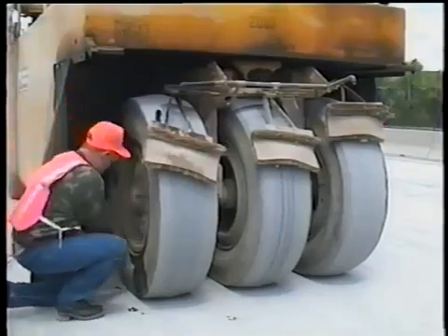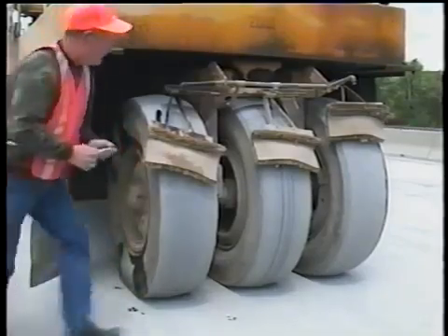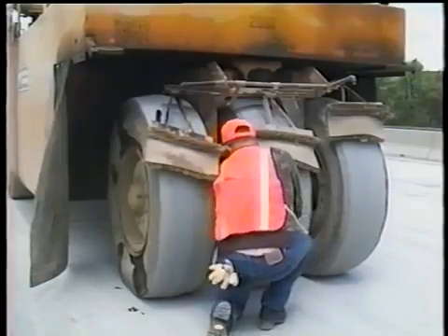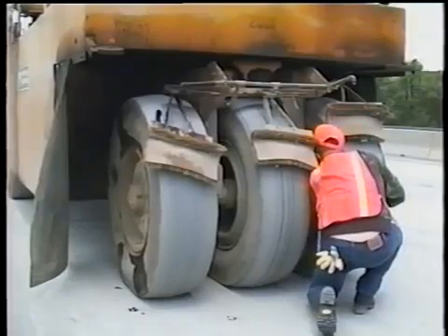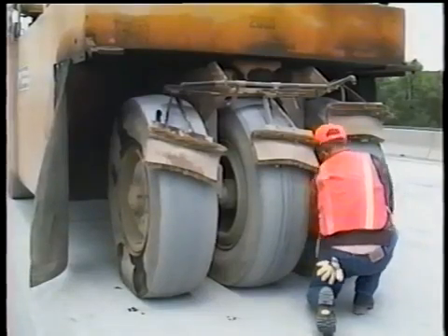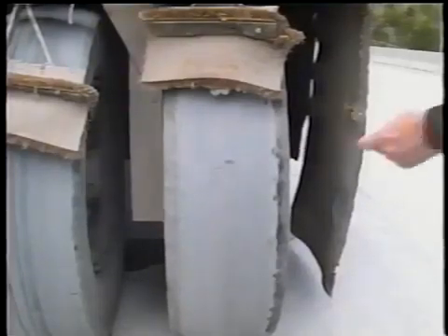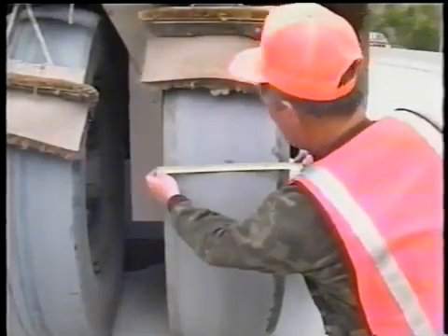Now let's look at pneumatic-tired rollers. Tire pressure greatly affects the performance of these rollers. All tires must be inflated to the same pressure within the tolerance suggested in the checklist. In addition, these rollers should have a working weight capacity of at least 115 kilograms per 6 centimeters width of tire tread. So measure the width of the tires and divide the number of centimeters into the total weight of the roller. Your checklist covers these calculations in detail.